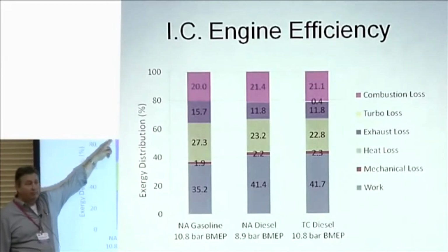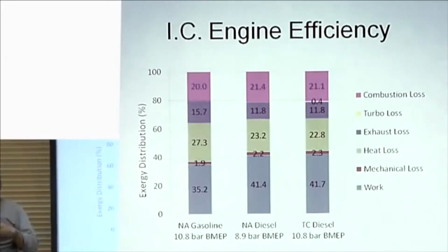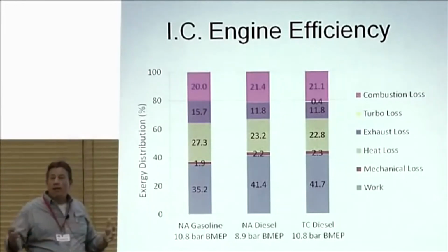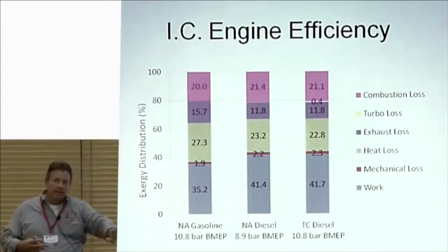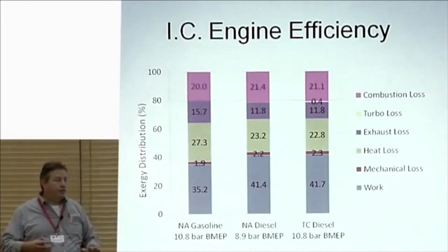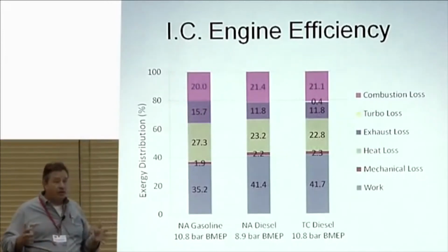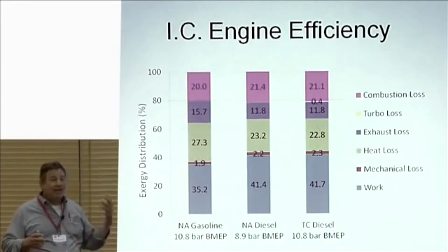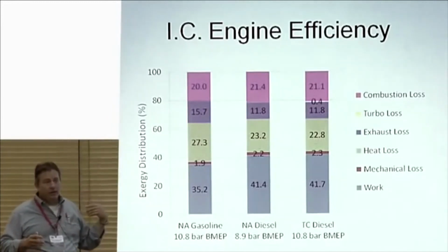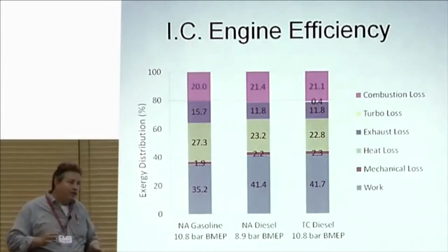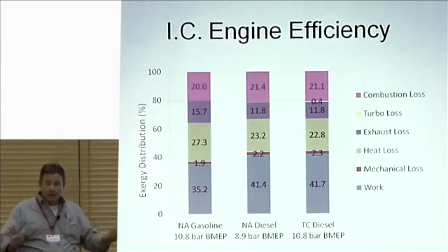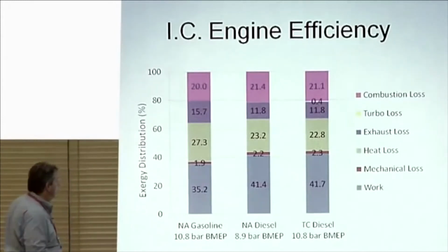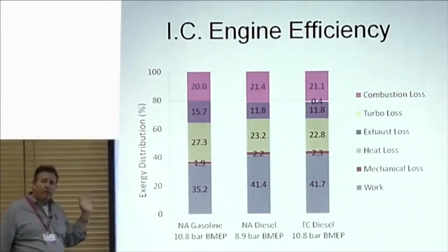And that's combustion. I mean, if I do combustion adiabatic, complete combustion efficiency, I go all the way either to equilibrium or take the temperature down and go to complete combustion from it. I'm going to incur about 20% destruction of Exergy because I used an irreversible reaction process. And I did it at relatively moderate conditions. If I take it to some slightly wackier conditions, I can cut that in half, but I'm going to leave that off the table for now. We'll keep compressions sort of reasonable for this. But it makes you think a little differently, right?